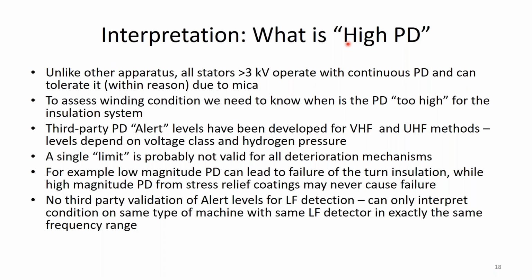you remember that white band I showed you on that hydro generator where the semicon had been electrically disconnected from the stress relief coating or the grading coating or the ECP. That sticks into the winding because of manufacturing issues. So when I got that, that produces exceptionally high levels of PD, okay? But in fact, it might not lead to failure anytime soon, if ever. Okay, so this is one of the things we're working on, to try and come up with databases or alert levels that are focused on each of the failure processes, but it's going to take a lot more data than we've got now.